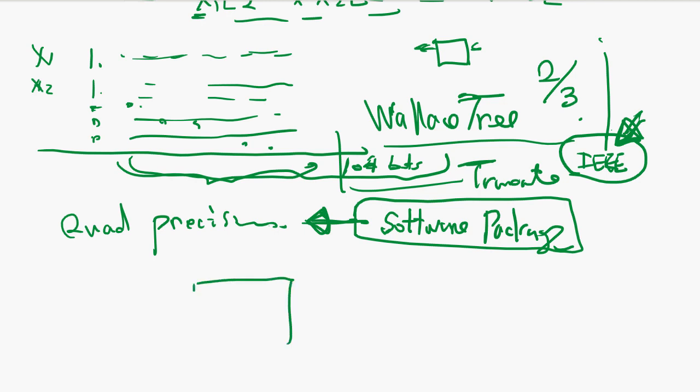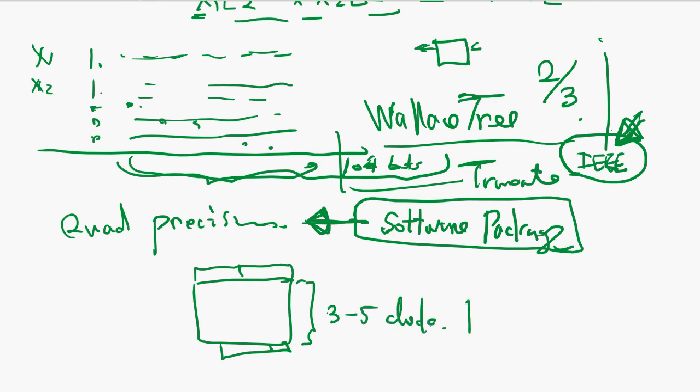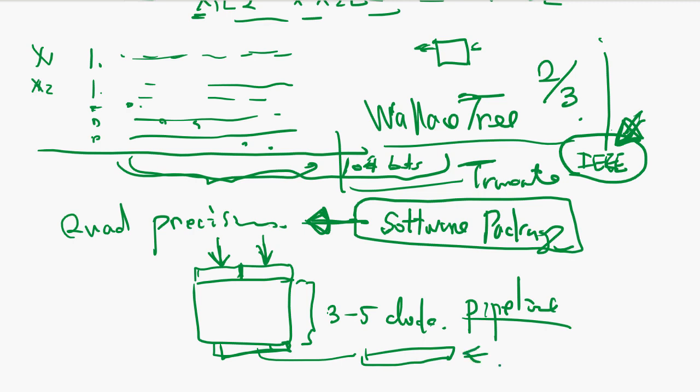Otherwise, this hardware is going to provide the flow through. You have an execution unit, you put number to number, and the answer comes out within maybe, on a fast chip, 3 to 5 clock cycles in pipeline fashion. So if you have a lot of numbers to calculate, you can just keep feeding and keep getting results. Every clock cycle you get a floating point calculation result.